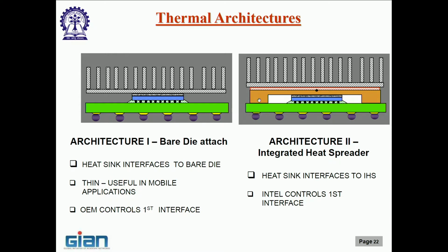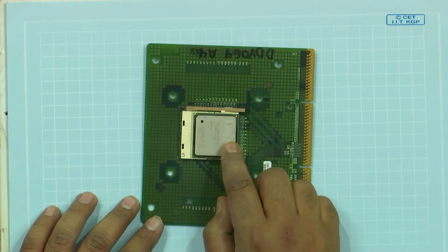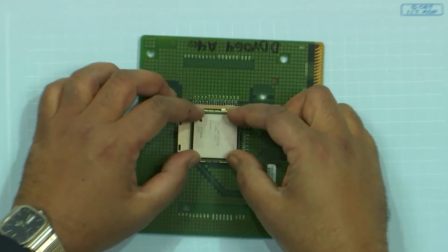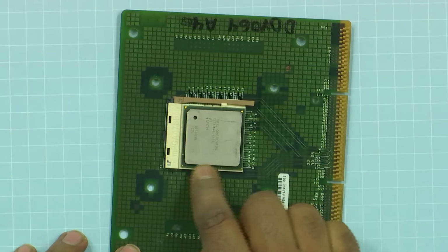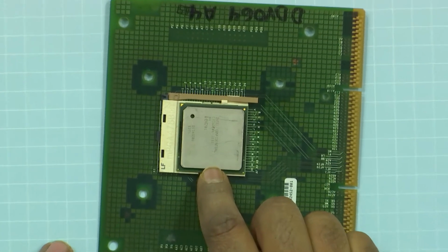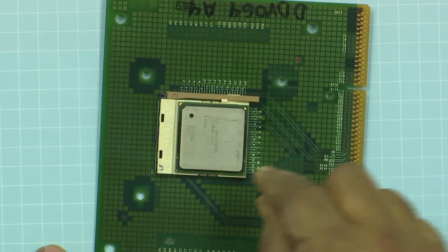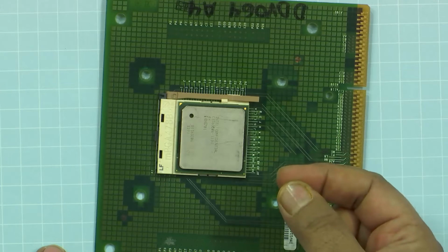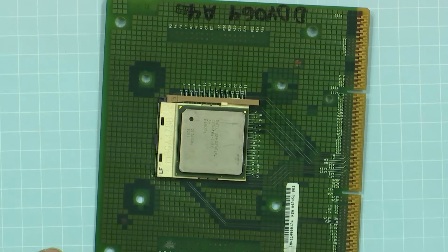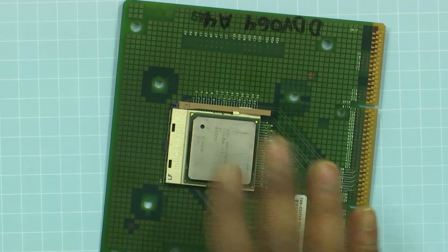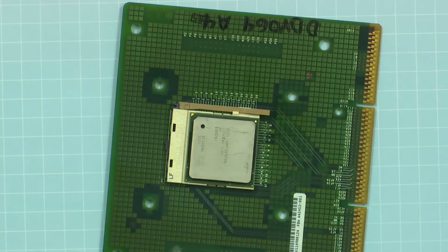So, if you now look at this package, this is a second type. What you do not see is the bare silicon die; what you see is this plate, which is the heat spreader or the lid, right. This is actually copper of some thickness, it will be 2 mm, 3 mm, I think 1.5 and 3 were the standards, and on top of that it is coated, because copper gets oxidized and tarnished very soon. All right.